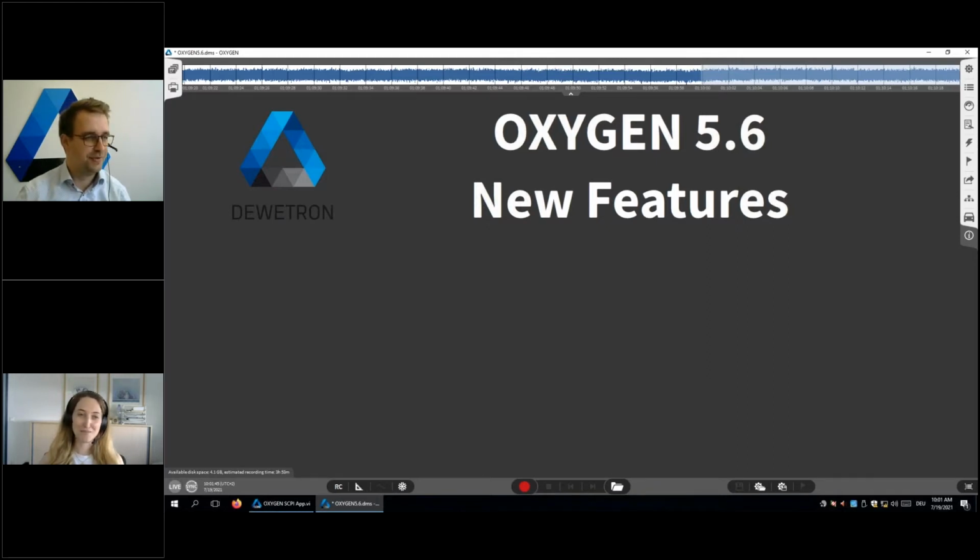Yes, just to be sure. Okay, perfect. Yeah, TEDs support. TEDs stands for Transducer Electronic Data Sheet, and is a chip which is implemented in the sensor, which reads out all the settings. And we are able to support that now. So we have 2 or 3 different modules which support it. Once we have the Trion 2402 DACC, where TEDs is supported, but only in the IEPE mode. So as you can see up here, we have this TEDs button, which is for this board.